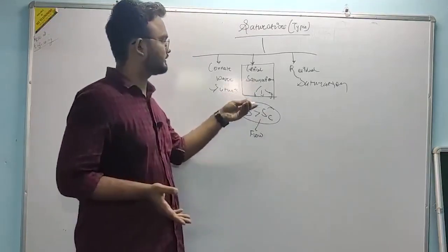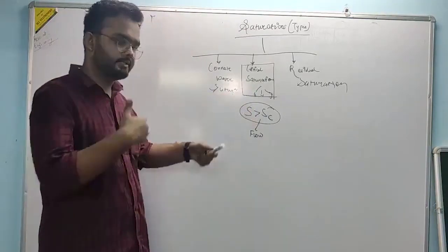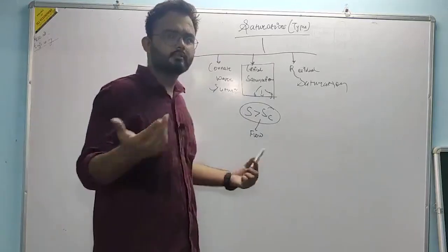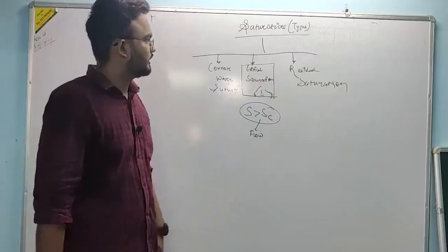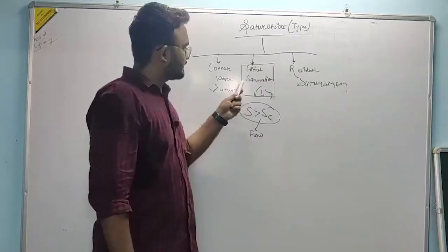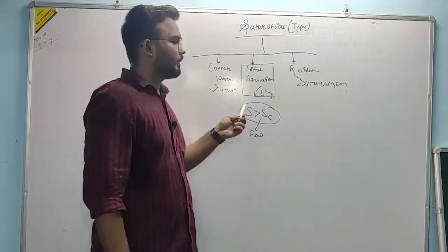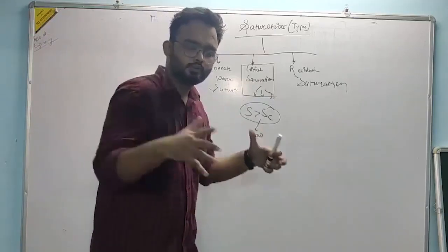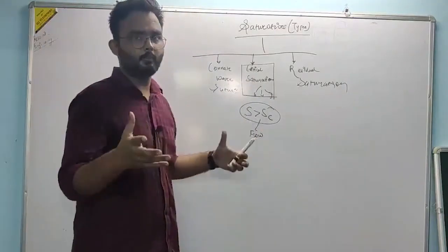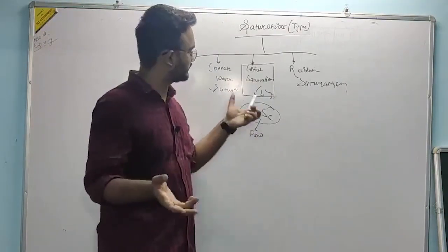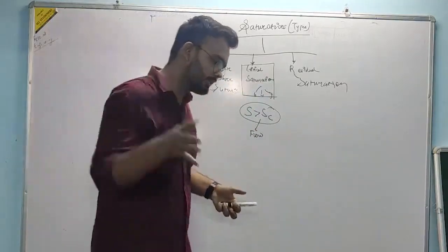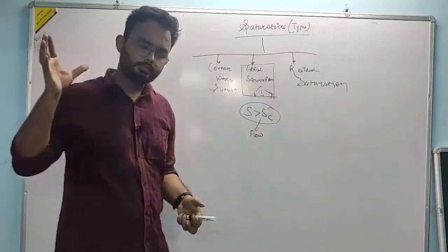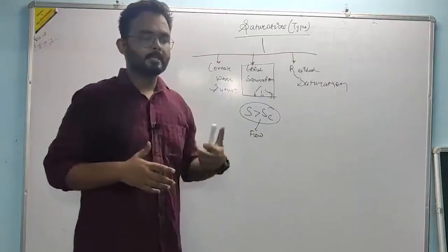If oil is at a saturation higher than critical saturation, oil is flowing nicely. Similarly for gas, similarly for water. However, you can see that this talks about the case where flow is trying to start. This perspective is important. Critical saturation is at the start. If you're trying to make oil flow, that is when we will be talking about critical saturation.